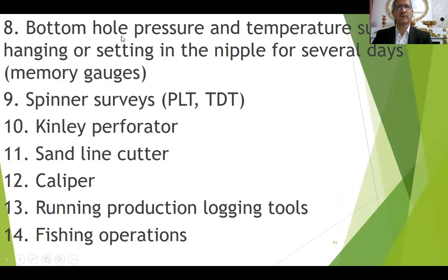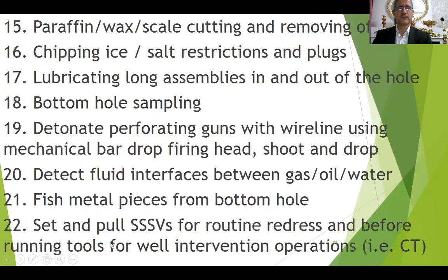Also, we have bottom hole pressure and temperature surveys, spinner surveys, PLT, production logging tool, TDT, thermal decay time. We have Kinley perforator if we need to perforate the tubing. We have sand line cutter, caliper, running production logging tools, and then fishing operations.